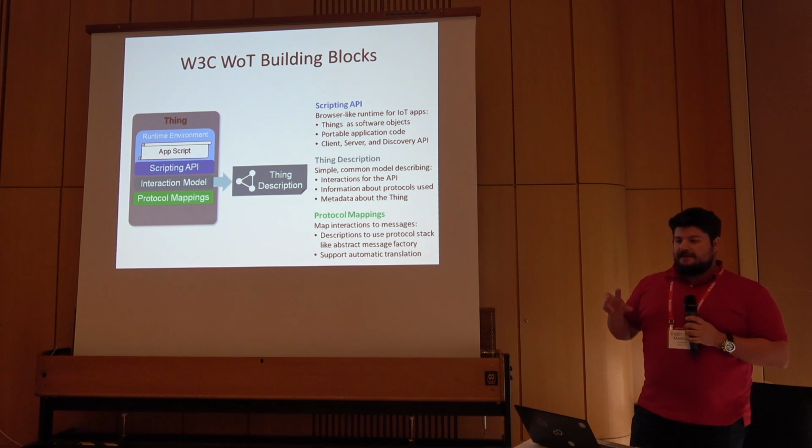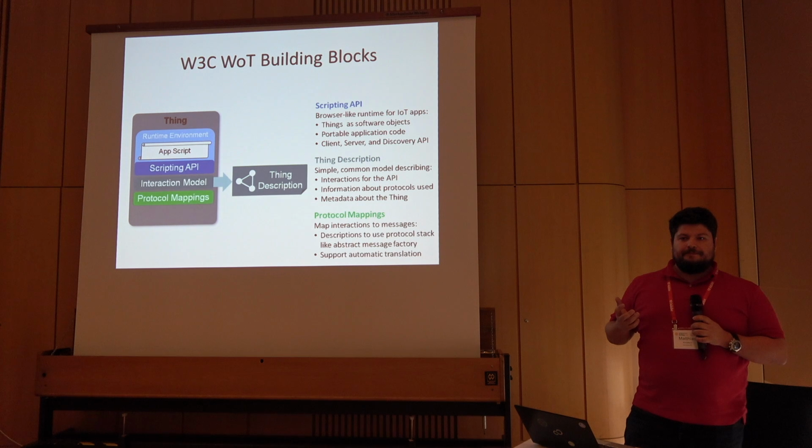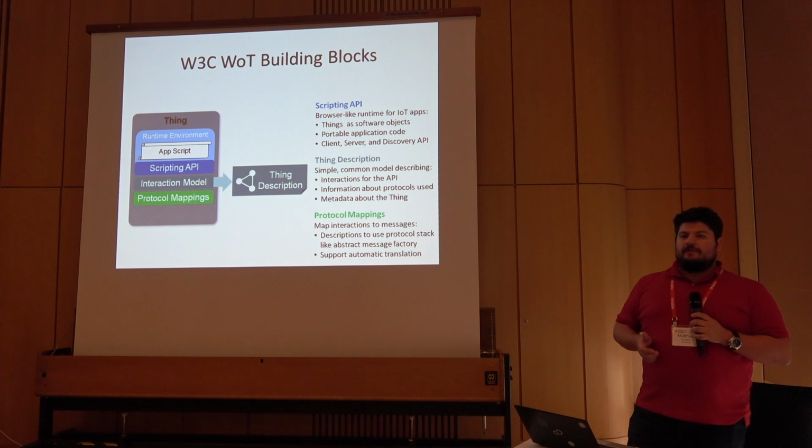And the nice thing is that this gateway automatically creates these descriptions, because we have a bridging ontology that understands the BACnet definitions and converts them automatically. So if we add a new device, we don't have to touch this gateway. And this automatic translation could help in many environments. For instance, we heard about the smart home project earlier, where we have exactly this problem. So at the moment, it's a lot of manual work and implementation to add new devices and add new features.